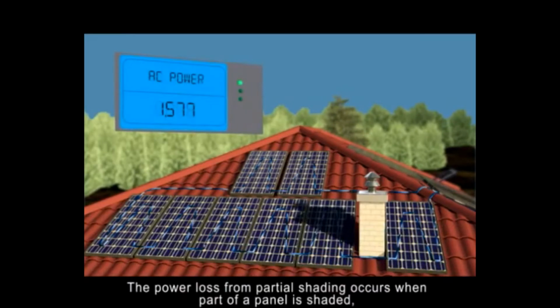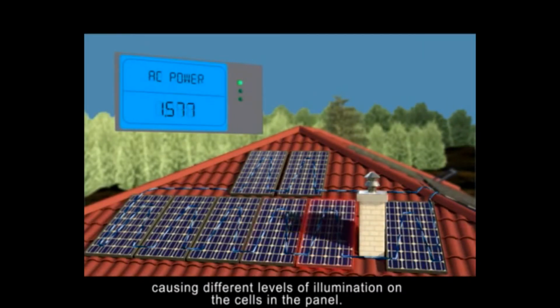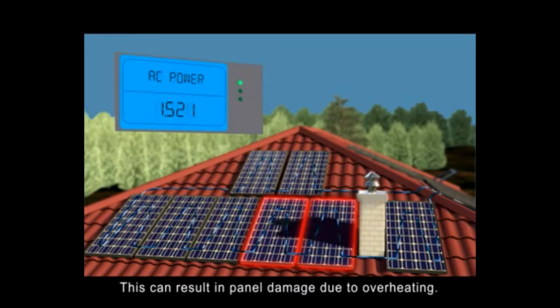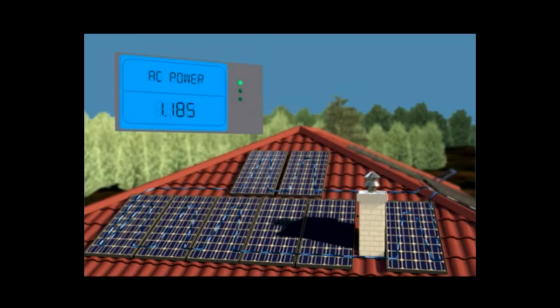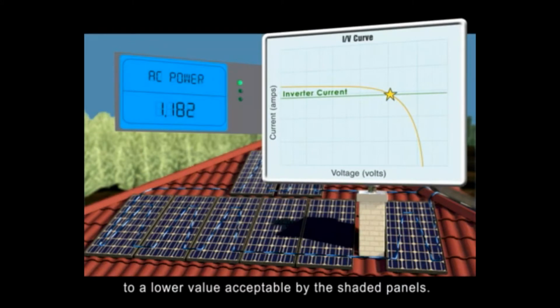The power loss from partial shading occurs when part of a panel is shaded, causing different levels of illumination on the cells in the panel. When a panel is partially shaded, its voltage may reverse. This can result in panel damage due to overheating. All PV systems prevent this in one of two ways. The panel bypass diodes conduct, causing shaded panels to lose from 1/3 to all of their power. Alternatively, the inverter readjusts the current flowing in the whole string to a lower value acceptable by the shaded panels.